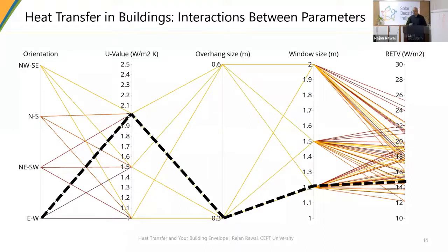So a lot of people make the cavity but do not make it a ventilated cavity, what happens is that air inside over a period of time attains very high temperature. And then that will not have any kind of insulating impact. This is including those coolers which they put on the rooftops. The cooler has very small air mass inside. And cooler is not a very insulating material.